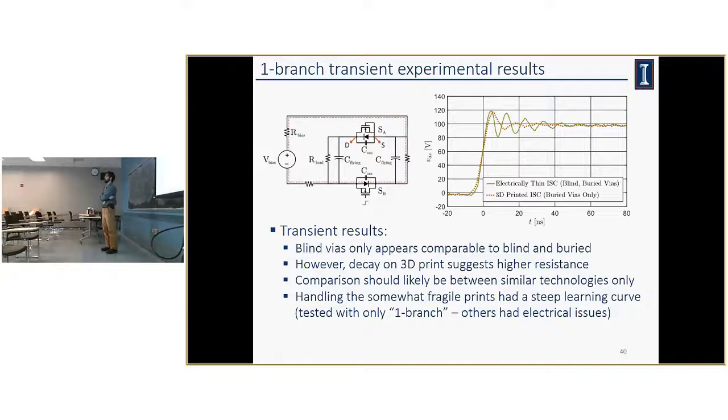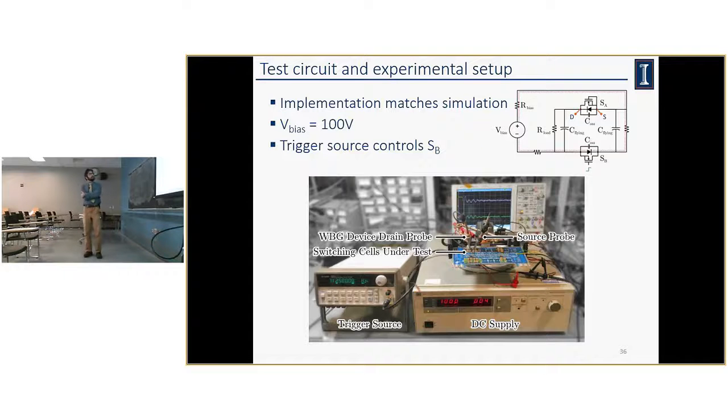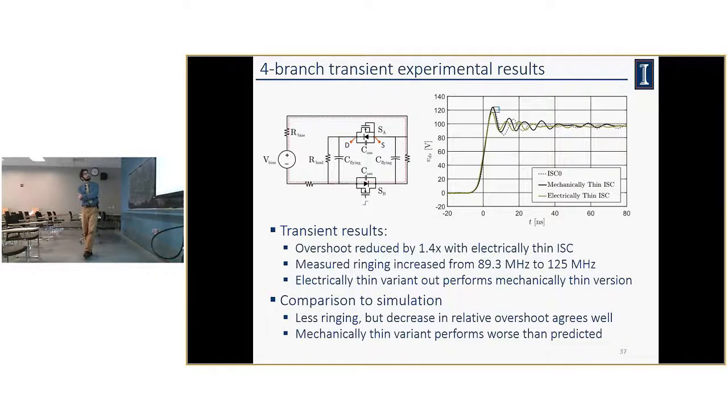Yes. I'm curious, in your experimental test setup here, do you have a bias current that you're switching between? A bias current. So in this case, there's a relatively high resistance R bias, about 200 kilo ohms. That's really just meant to ensure that there's some amount of current trickling through this diode so that this COSS is discharged and so that this COSS is charged.